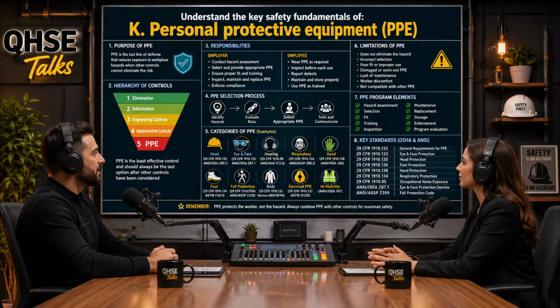And you must ensure the goggles are chemically compatible. If you are working with strong solvents, certain plastic goggle lenses will fog, craze, or just straight up melt. What if a worker wears prescription glasses? Then the goggles must be specifically engineered to fit cleanly over their glasses without compromising the facial seal around the arms of the glasses, or you must provide goggles with custom ground prescription inserts. Okay, the third category is the face shield. But here is the trick from the study guides.